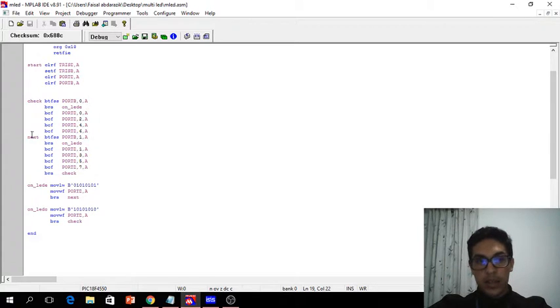And it will branch out again to next. So whenever it branches out again to next, we have to turn off the button first. You have to turn off the first button because that button is still on. Whenever it branches out to next here, the next button is still set. We didn't press that button, so it will go directly to port D to clear everything and go back to check. In case you press the second button and both were working together, it will just go crazy.